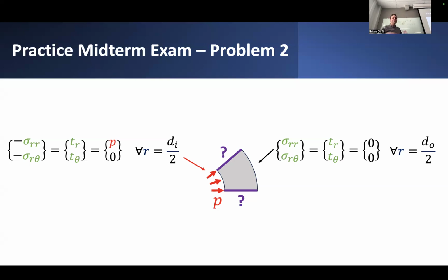So we now have a mixed collection of boundary conditions defined on these symmetry planes. We have both that the normal displacement, or displacement in the circumferential direction, on both of these planes has to be equal to 0, and that the shear components of traction acting on these faces are also equal to 0 to allow the points to slide freely along those interfaces.